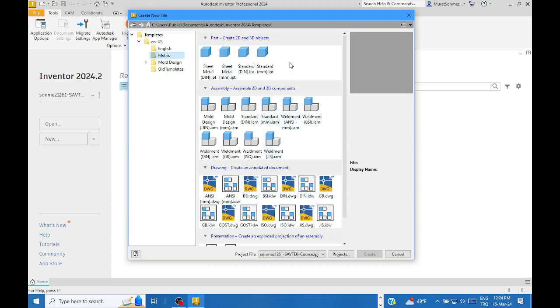For creating the model of a single component, that is the template option to select. It says Standard, but we know that this Standard is ISO, the International Organization for Standardization. Making the selection on this template option, Inventor concludes that yes, you are going to obey the rules of ISO. The unit is millimeter, etc., etc.